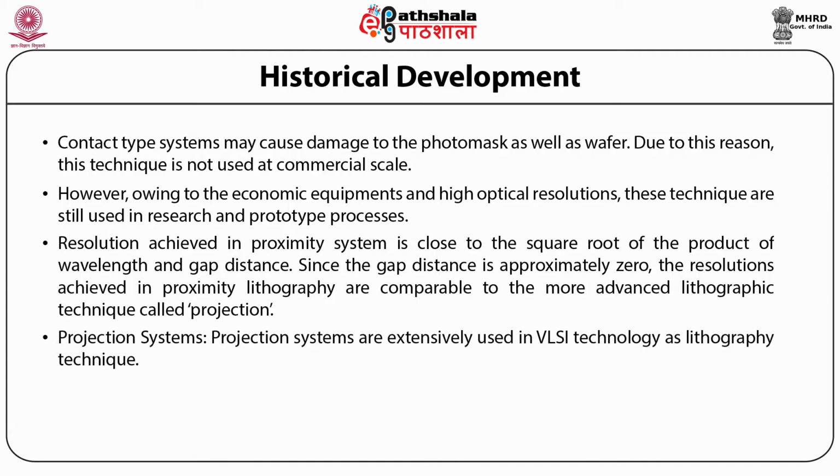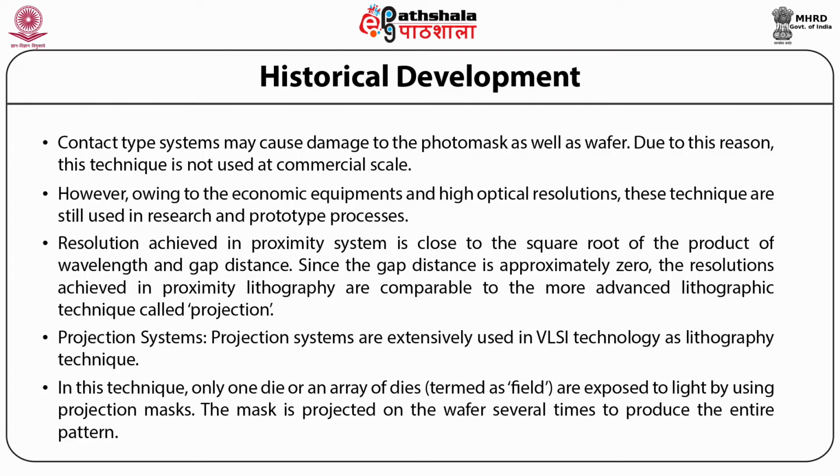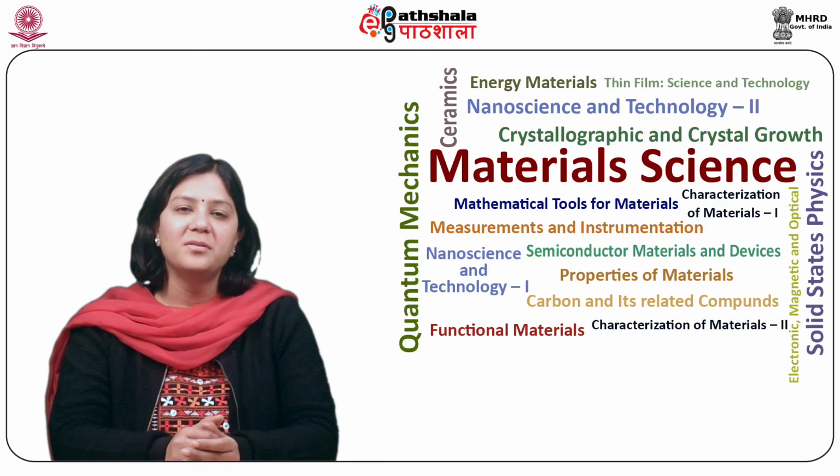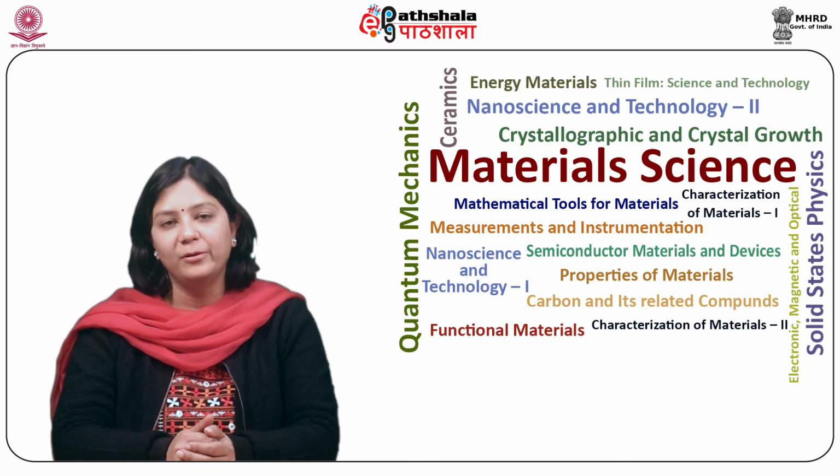Projection systems. Projection systems are extensively used in VLSI technology as a lithography technique. In this technique, only one die or an array of dies are exposed to light by using a projection mask. The mask is projected on the wafer several times to produce the entire pattern. Now let us study the photomask.